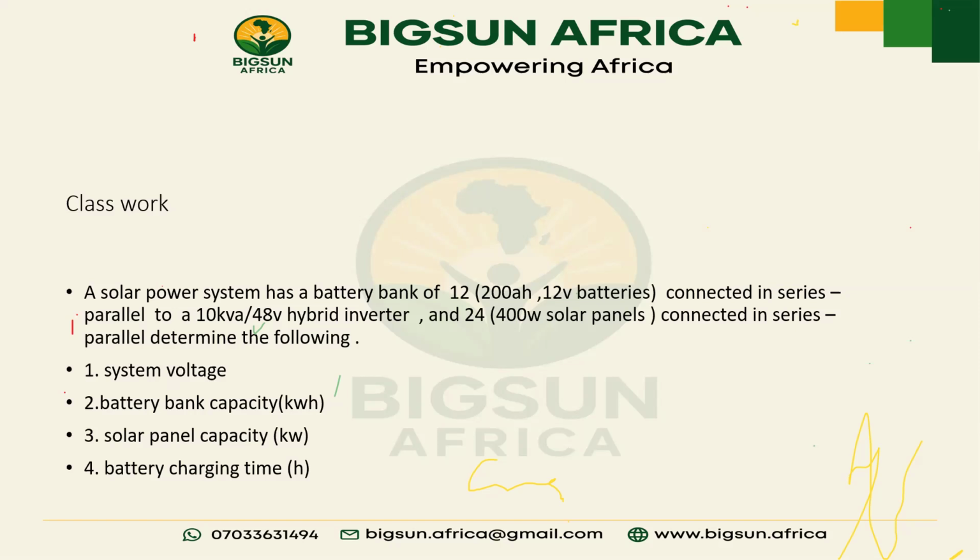So if your charge time doesn't fall within this PSH, your battery might not get filled up before the day runs out, or you are going to use NEPA to commensurate it, which is not efficient. You don't include NEPA in your designs, except where the client tells you, okay, this is what I can afford for now, let's use NEPA to augment it until I can go full solar.